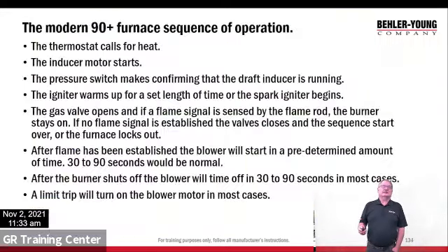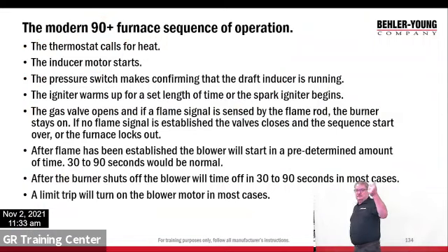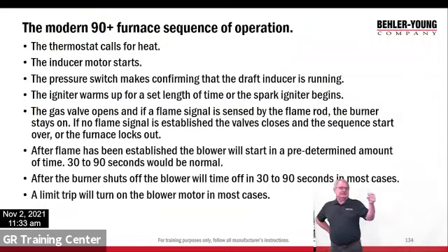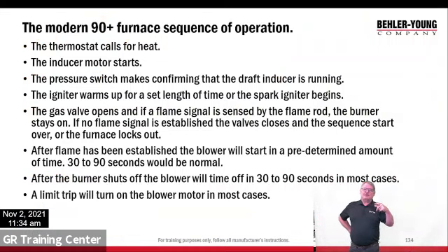Okay. All right, so the modern 90% furnace sequence of operation. Now, this is pretty standard, regardless of which variety you're working on. Thermostat calls for heat, the inducer motor starts. First and foremost, makes a pressure switch or draft switch. Igniter warms up or the sparker starts, whichever begins. After a set amount of time, the valve opens.